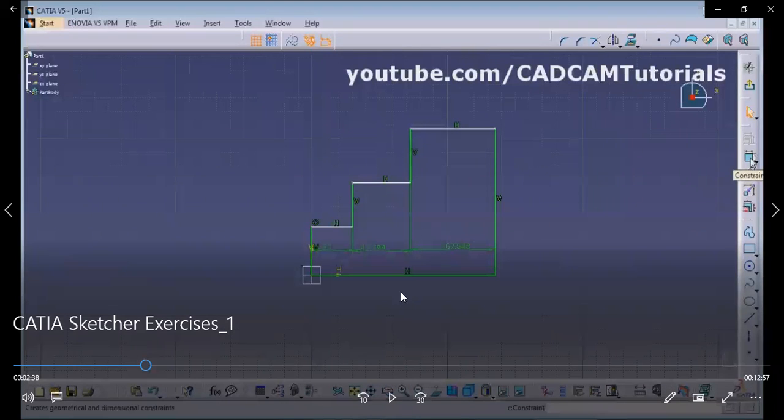So if we specify this one, this one and the total one, it is fine, because the software can calculate the remaining distance by subtracting the sum of these two from the total. If you have also specified this along with the total distance, then it becomes over constrained.